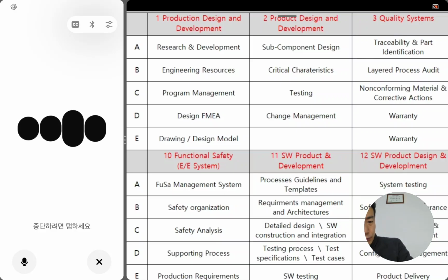Because we are an automotive camera manufacturer, DFMEA is organized into four main sections: hardware, mechanical, software, and optical. DFMEA activities are performed by a cross-functional team, including R&D, quality, and relevant engineering functions. Potential failure modes are identified and evaluated based on severity, occurrence, and detection, and appropriate mitigation actions are defined for high-risk items. DFMEA results are documented and managed in our PLM system, so they are fully traceable and accessible to all relevant team members. These DFMEA outputs are also used as key inputs for PFMEA during process development.